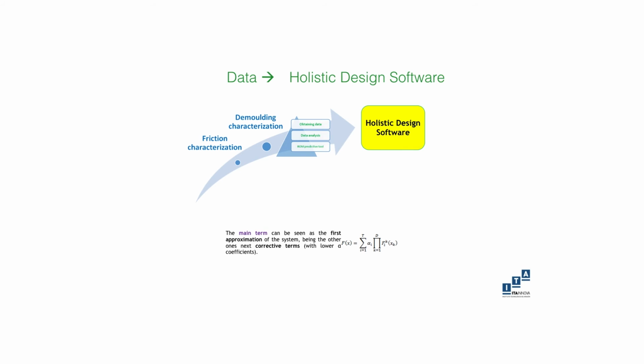In particular, reduced order modeling is a numerical method for multivariable problem simplification, which dramatically reduces the computational cost required for solving complex numerical models and synthesizing experimental data. Our approach aims at describing and hence predicting a system's behavior through a mathematical approximation, preserving its main characteristics and physical parameters.